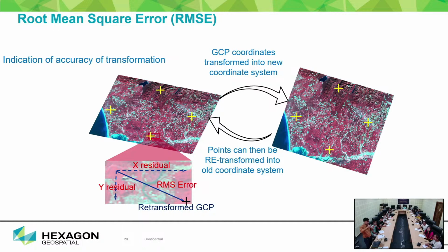These are the actual locations of the ground control points, GCPs, and after the correction the image orientation has changed and exactly fits the ground view of the data. When you use the resampling or georeferencing method, some error will come, because after resampling the data will shift somewhere, and these errors should be minimized to the minimum level.